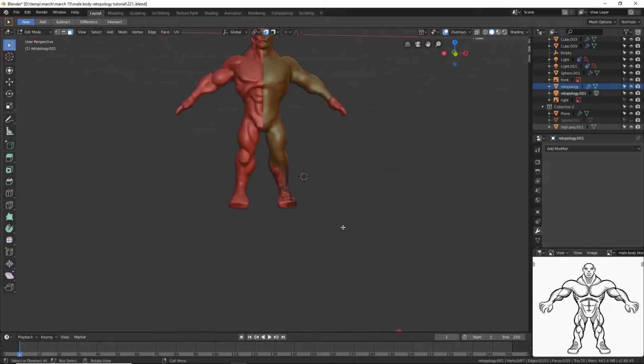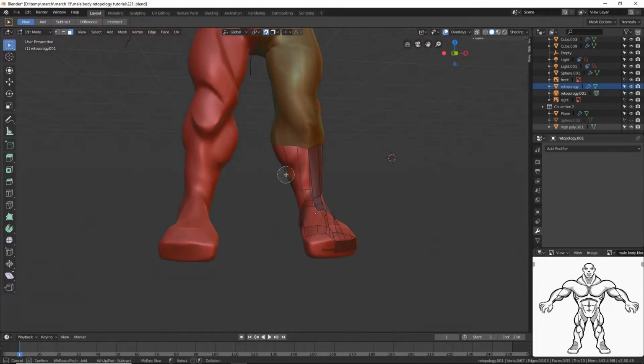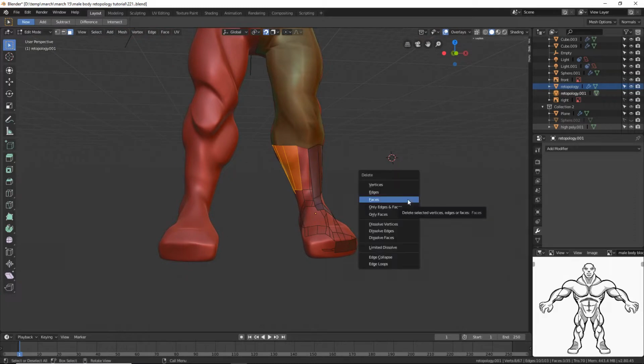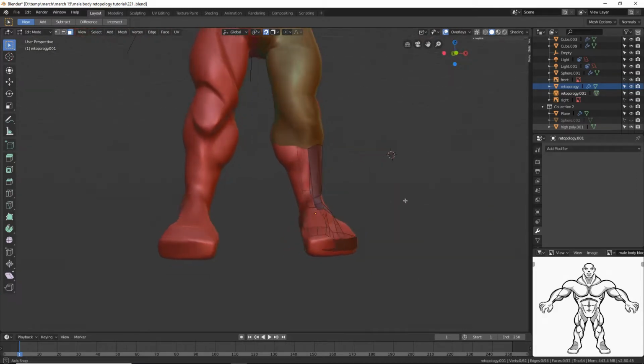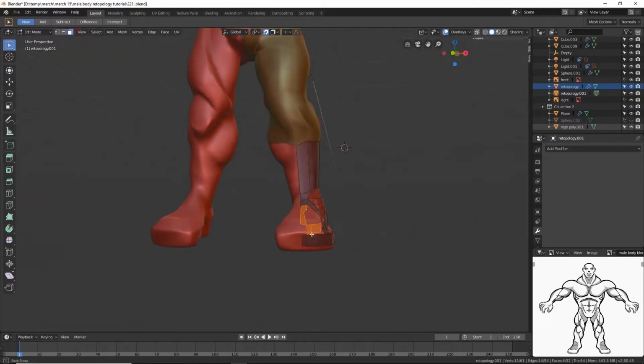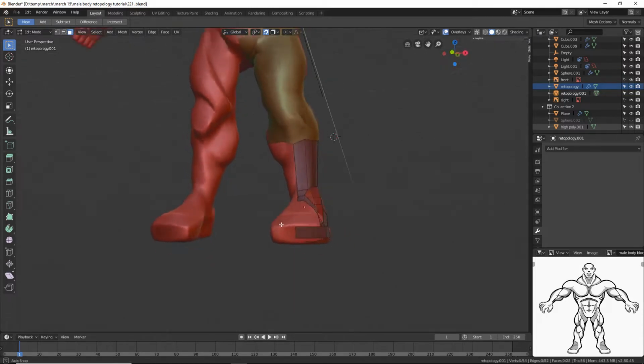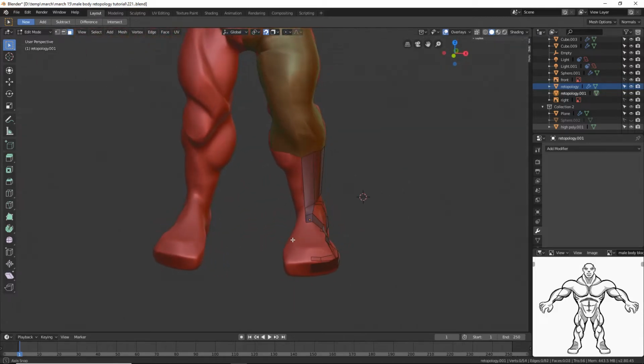That's Blender jumping there. We have this geometry here, so I'll press C. Press X to bring up our delete menu. Same thing here, we'll press C. Press X to bring up our delete menu. So I think we have half of the geometry now.